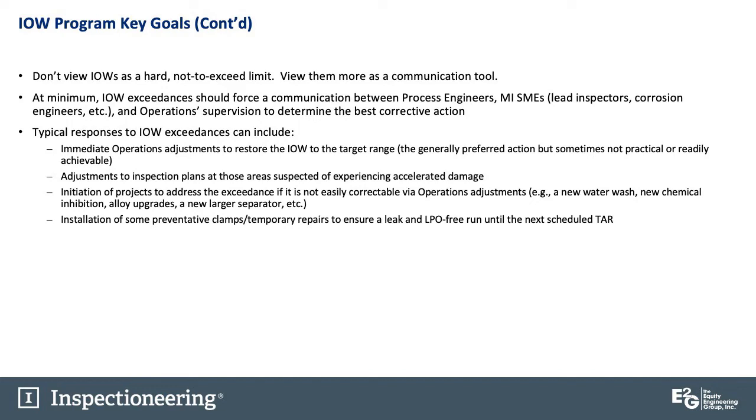And at minimum, IOW exceedances should force a communication between your process engineers, your mechanical integrity subject matter experts, such as lead inspectors, corrosion engineers, and operations supervision to determine the best corrective action. That's what we want to do. We want to get those people together to determine the best corrective action through an IOW exceedance.